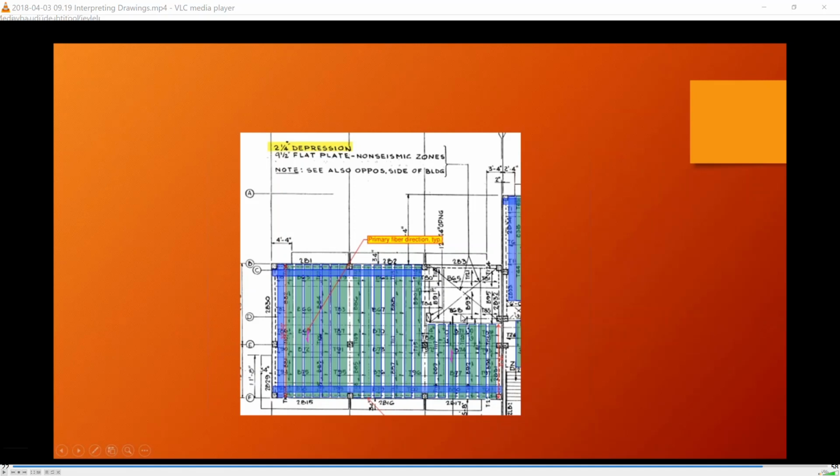And then in the architectural drawings that Brad was showing us, I think we talked about that in the NCR discussion the other week, that sometimes you need to look at architectural drawings, but normally you don't. Ideally, everything would be in structural drawings, but the biggest reason to look at architectural drawings is for dimensions, and specifically floor heights were the ones Brad was showing us.